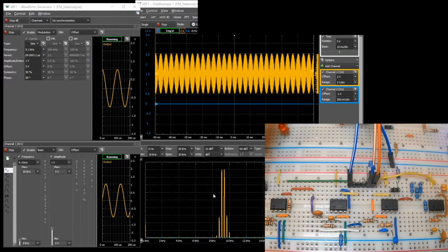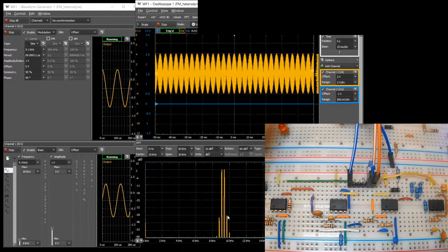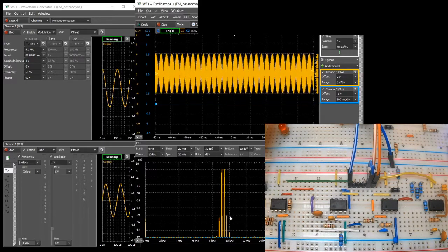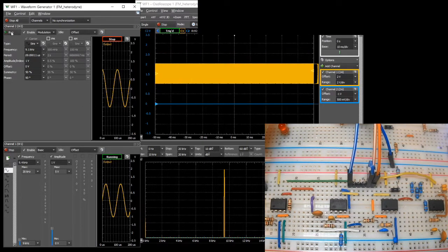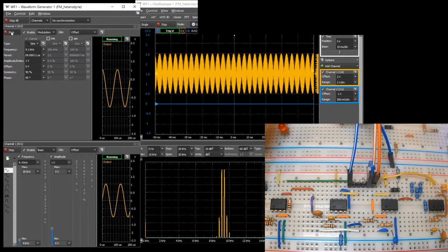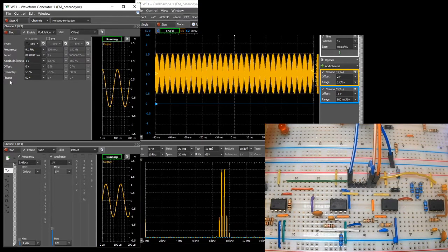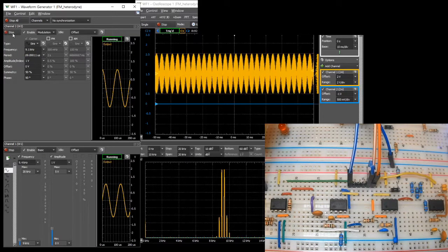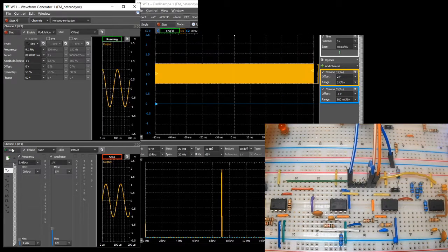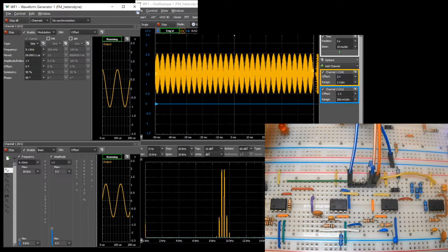Its Fourier spectrum consists of two main components. The nonlinear components on the sides are more than 40 dB, that is, 10,000 times lower power compared to the main components. The nonlinear mixing components can be identified by simply switching off each signal alternately. The components that exist only with both signals are the nonlinear mixing components. As evidenced, there are only a few nonlinear mixing components, and their power is relatively low.